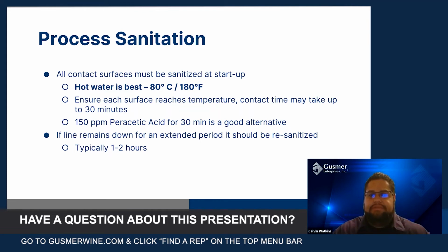A good alternative to hot water is 150 parts per million peracetic acid for 30 minutes. So that's a good alternative. Again, the ideal thing is to get all surfaces treated for 30 minutes. So it's time and either temperature or chemical.